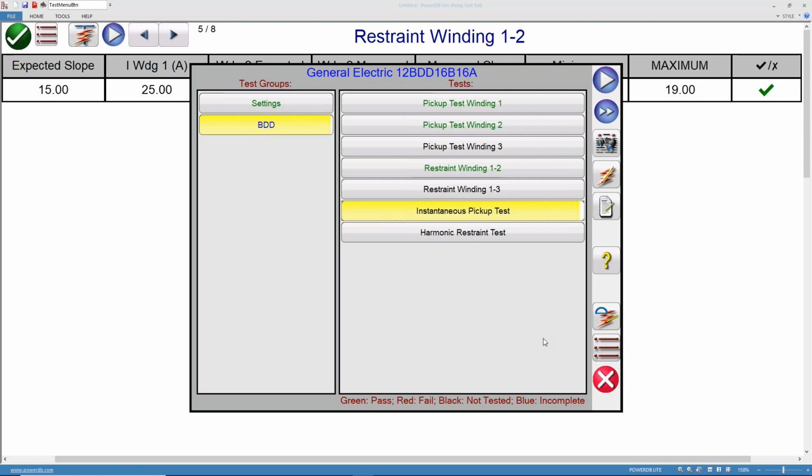Well, the answer is of course you need to test when you have a relay and you have 3 windings, like the relay that David was showing there. If the 3 elements are being used, because you have, like you say, a 3 winding transformer, then you need to test all the elements that are enabled in the relay at the moment of the testing.